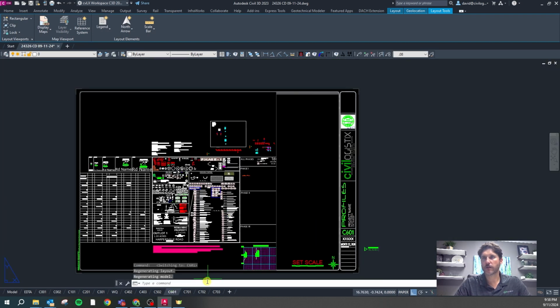6 is for profiles if you need to. We try not to do too many pipes on residential plans because residential people typically don't clean out their storm pipes very well, and so we don't want to rely on a pipe to keep someone's house from flooding, knowing that they're not going to keep the pipe maintained properly, and then they're going to have drainage problems. So we'd rather design the residential projects with swales and ways to convey the water above the ground, because you just don't have to rely on pipe maintenance. So a lot of times you're going to delete this sheet on projects.